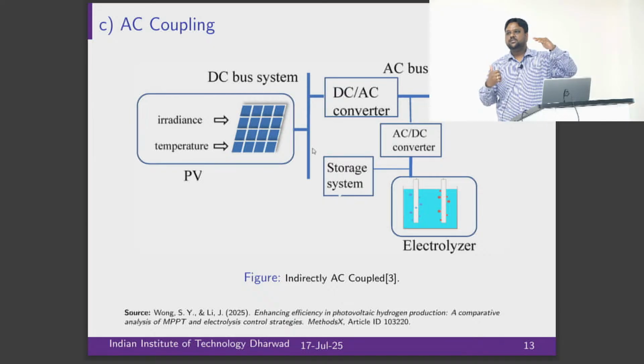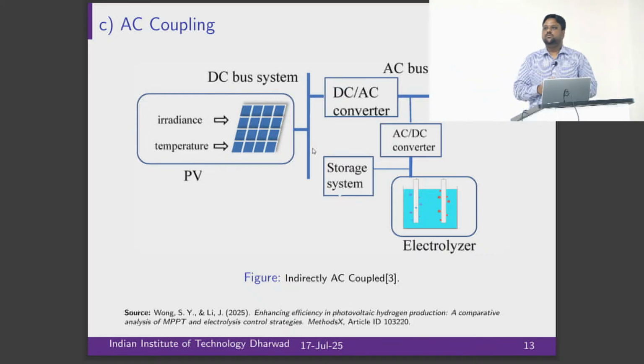and hydrogen will do the job of controlling its active power based on the frequency. That's why we call it a flexible load, not a simple passive load, R load or inductive load. It will help to maintain the solar at MPPT, but when a frequency event happens, it will give the active power, because this electrolyzer will not be required to operate always at 100% capacity.